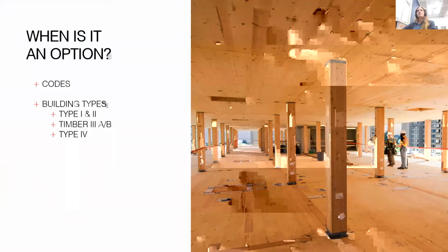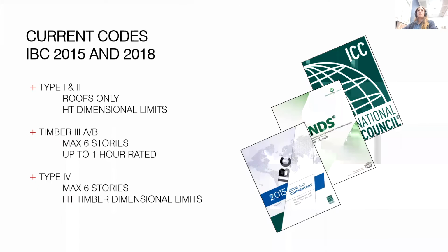So then there's this idea, okay, these are all the reasons why we're considering timber, but once we know all of these benefits, when does it make sense to introduce timber as an option when you're looking at different buildings and performance and requirements for buildings? So the current codes, typically in most places, we're pulling from IBC 2015 and IBC 2018. In these codes, timber is allowed in most types of construction, but